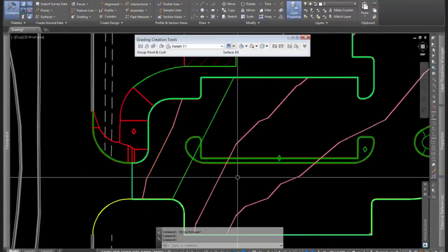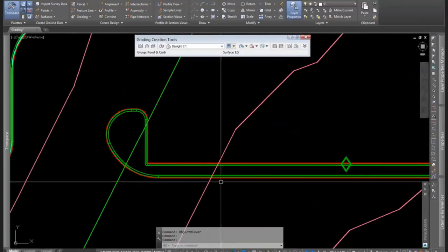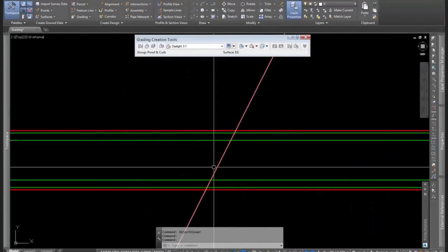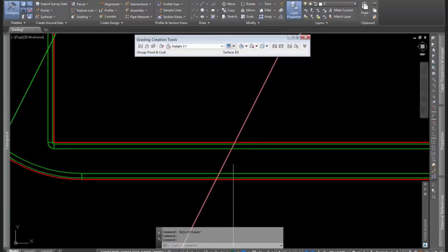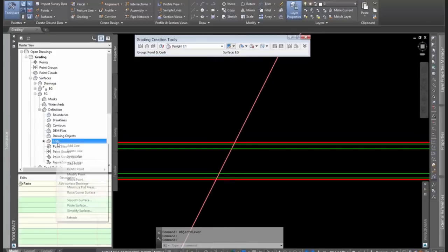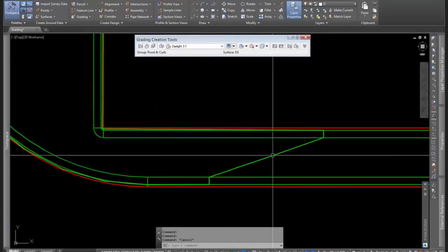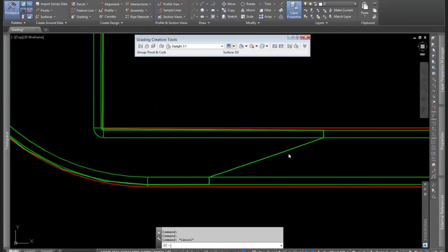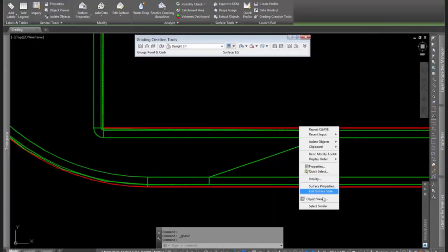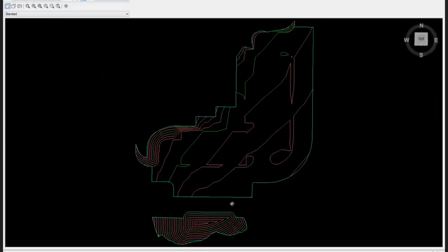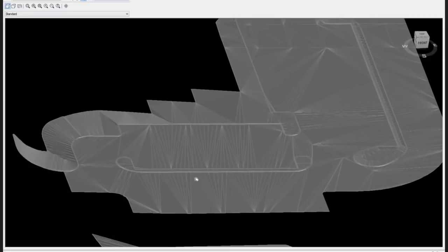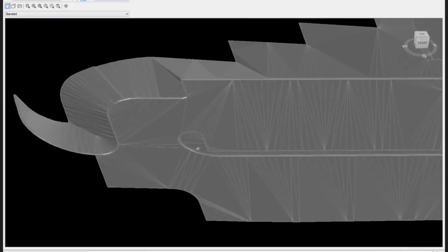Now here's the key. You paste drainage first and then your curb second. In these areas where it overlaps, the last one pasted will control. So here's what that looks like. If I go in and paste in my pond and curb surface, now it trims that out, and we get a combined surface. Let's open this in Object Viewer again, and we get one surface. Okay.